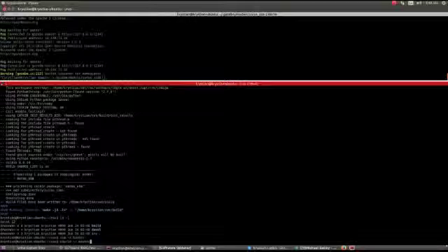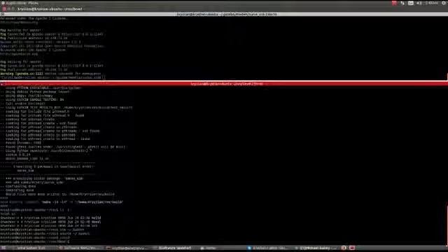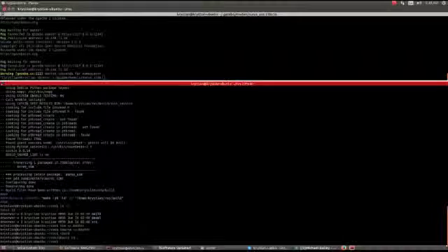So here I'll comment out the other workspace that I had, and below here I will add the path to our Catkin workspace. So it's going to be in the ROS folder that we created. The devel folder is generated as well as the setup.bash script file. We will want to source this, so we want to go back and re-source the bashrc file. So now if we type roscd, we should get to our Catkin workspace, which we did. And now what we will want to do is simply go in and launch the gazebo.launch file.